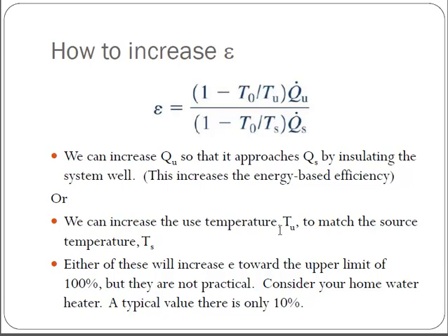Now, just one little practical point though, think about like a home water heater. Most people do insulate their home water heater, but nonetheless, you still only have an exergetic efficiency of roughly 10%. Most of that heat is just being lost to the surroundings. So there's a lot of room for improvement in our everyday life. And as an engineer, we can look at ways that we can make those improvements, and one of the first things is having the available tools so that we can actually quantify these. So that concludes my videos on Exergy.